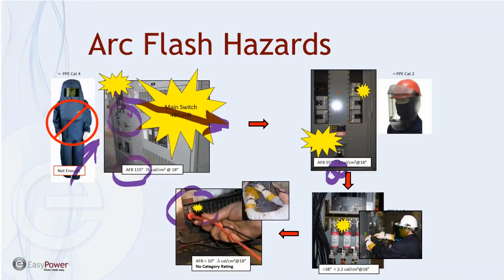So it exceeded 1.2 calories, and that's something to think about. But the rubber gloves should have been used to do that particular job, which would then provide protection for arc flash as well. So as I mentioned, 3 or 4 levels down from the main disconnect is usually under 1.2 calories, just as a rule of thumb.